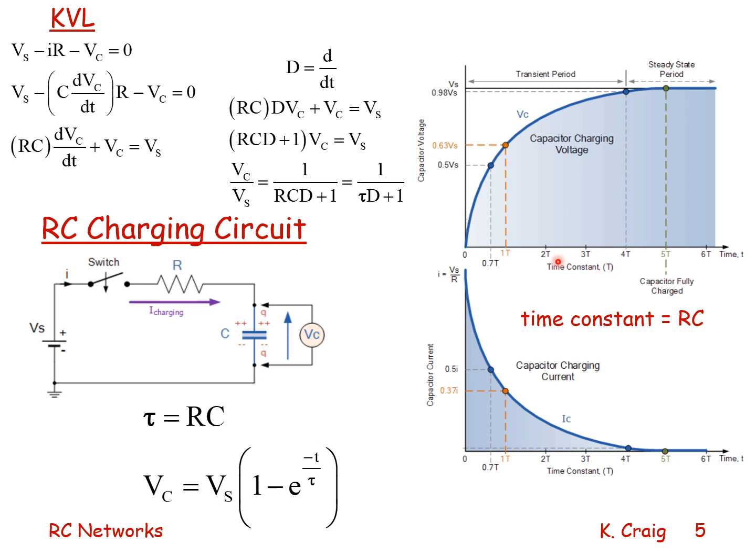Capital T is called the time constant, or normally we use the Greek letter tau for time constant, which is the product of R times C. And at that value of time in seconds, the time constant, the voltage across the capacitor is 63% of its way towards steady state, towards its maximum value, which is the voltage of the voltage supply.